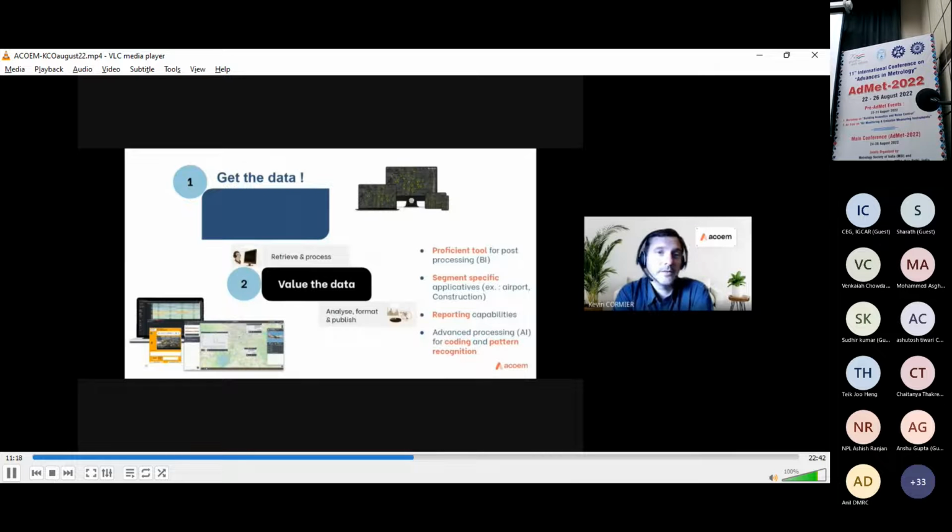The second step is to value the data. Transforming this huge amount of data into relevant information and insightful synthesis is certainly the most critical challenge for a noise monitoring engineer. Making the most of exploration and analysis techniques is certainly the key. More and more embedded algorithms with advanced signal processing, like noise source recognition, are supporting experts. This is actually the lever which has to be triggered to get efficient analysis and shorten the path between measurement and action.